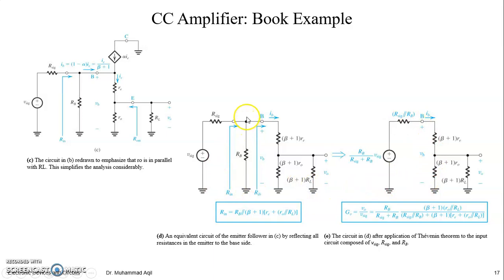So they actually, what I said here, we use that version. They actually said how to reduce this circuit further. So they said let's Thevenize here. So they Thevenized here and a resistor and a voltage source, right? This one. And then they found that this resistor and this resistor and these parallel combinations would be the remaining network, and they derived these formula. We can prove that this formula is similar or same as we found, right, by putting all the values of Rn and other things, right? But we don't need to do that, right?